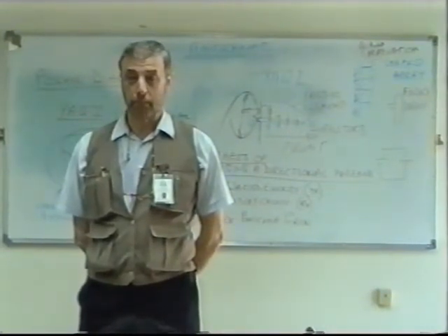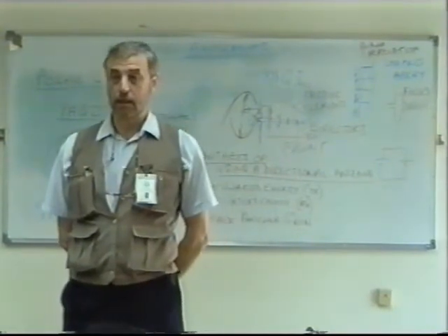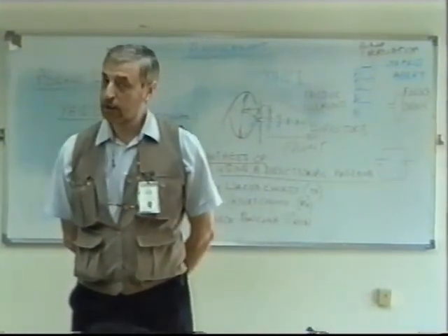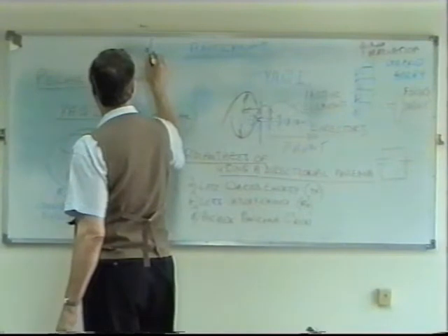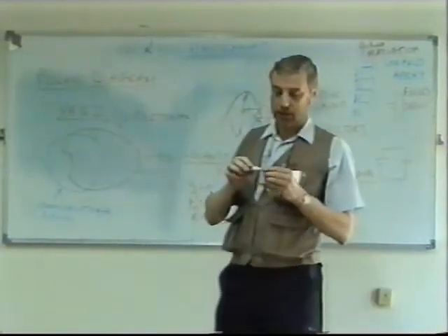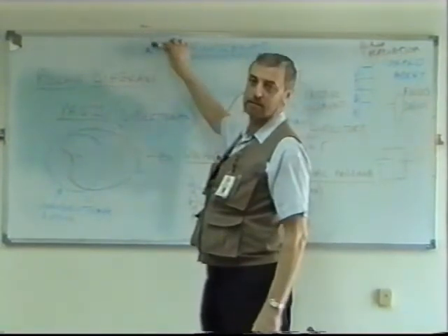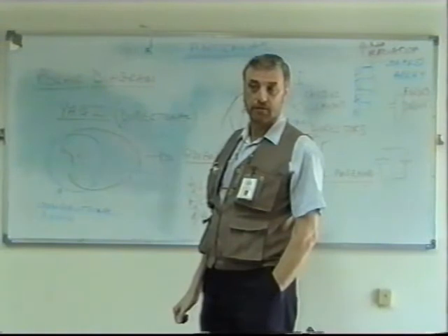The antenna of the cordless telephone, it's a dipole. The feed point can be towards one end; it doesn't have to be in the middle. And depending where you feed it, all that changes is the impedance matched to the transmitter. Is that going to be a quarter wave?